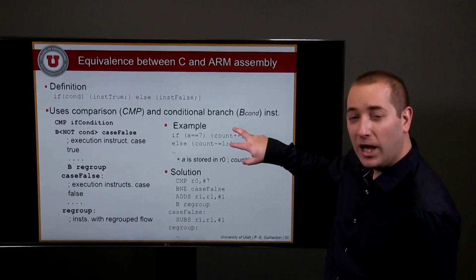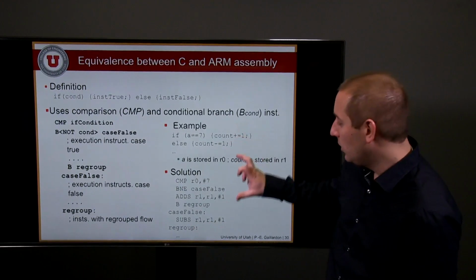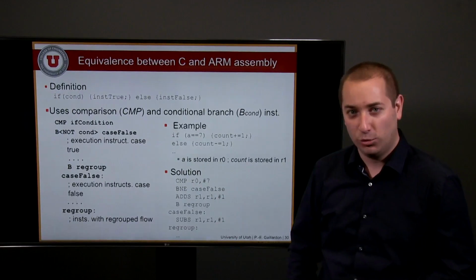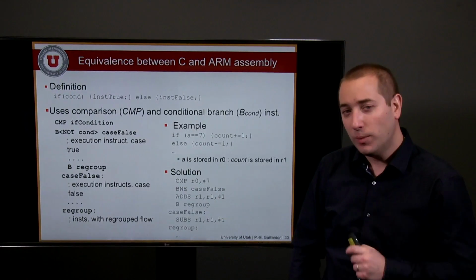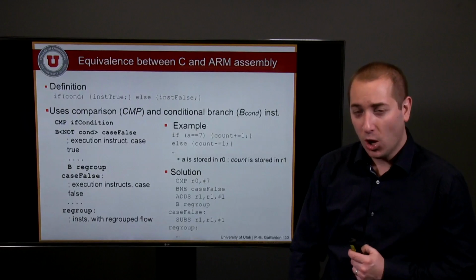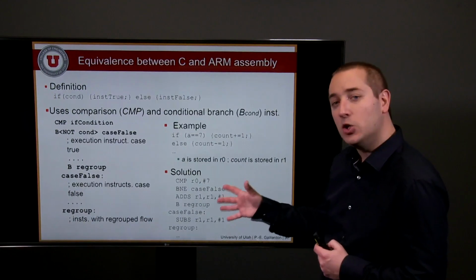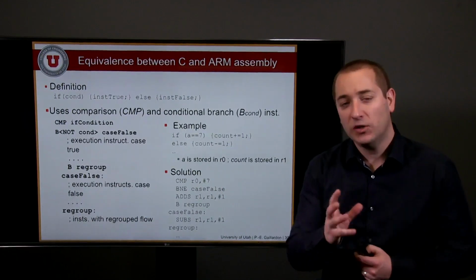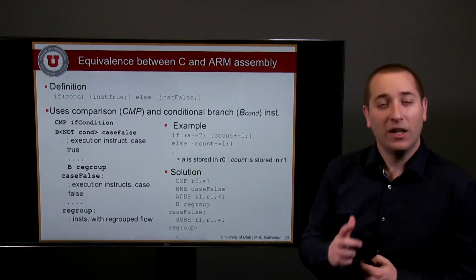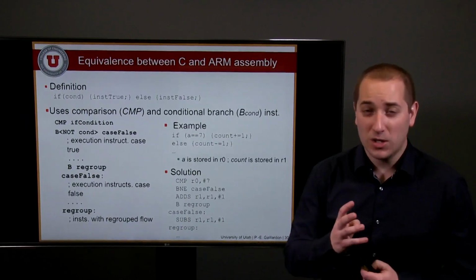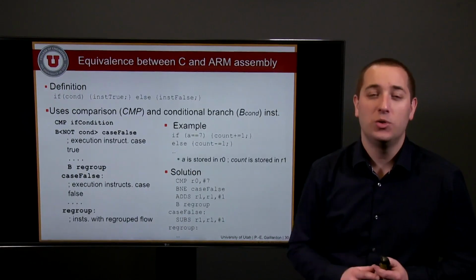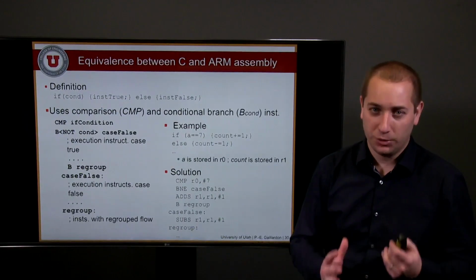So with these 2 lines, very easy pieces of C code, I can replace a more complex subroutine. You do replace this complex subroutine when you write your code, but it's effectively translated into this kind of solution. So you must keep in mind that any bad C code will end up with a bad assembly code. So you need to take a lot of attention in your C code and understanding what you do.